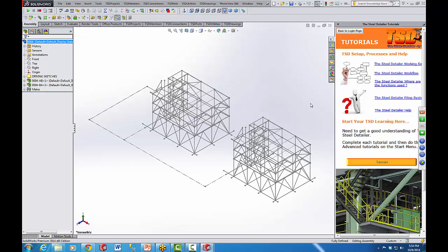And the top level driving sketch, you always want to set it up so that the person who's running the project, who looks after the interfaces, is the only one that can access that driving sketch. The other people in your project do not want to fiddle with this driving sketch. So this is all just model management and multi-user environment management.